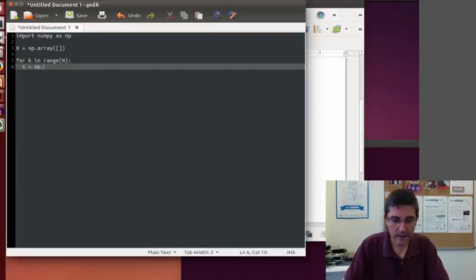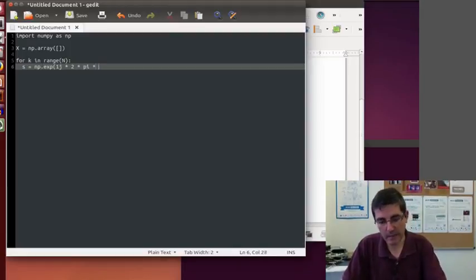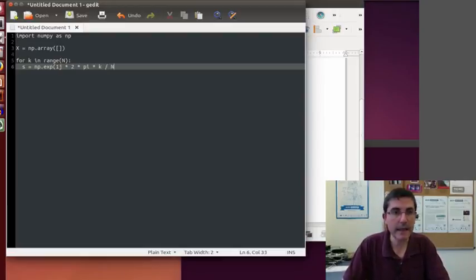So we'll create a complex exponential times 2 pi, multiplied by the frequency we want, and we need to divide by capital N. Then we need to create it for all n, so we will create an array of time sample indexes that will go from 0 to N minus 1. And that's a complex exponential at frequency k.